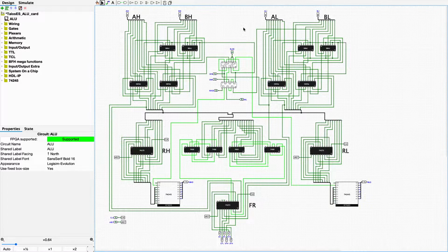That's RISC for you. You don't have microcode and state machines to go through all this, because every element of the machine is being used every cycle. In CISC, only the elements used by a certain cycle of the microcode state machine are being used, and all the others are being wasted. In RISC, everything is being used all the time. Almost everything is being used all the time.